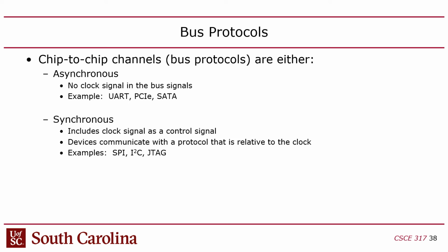And by the way, when I say channel, channels are usually multiple wires that work together to create a protocol, right? For example, a DRAM channel has maybe 200 or so wires as part of it, right? That includes the address wires, the data wires, and the row access strobe, column access strobe, clock enable, and all that other stuff, right?